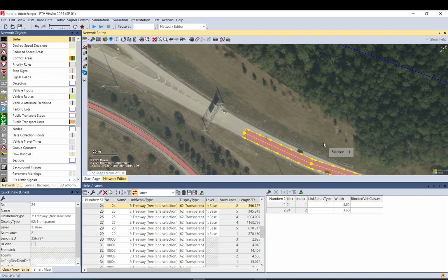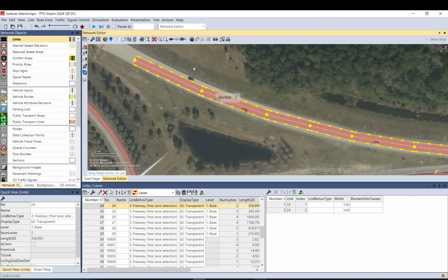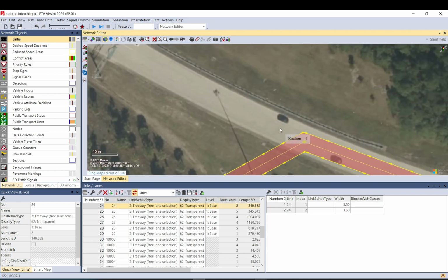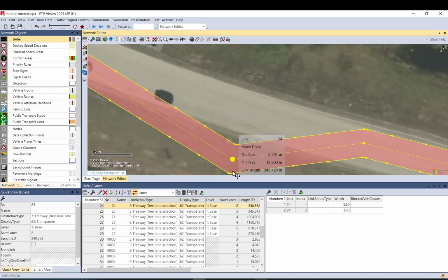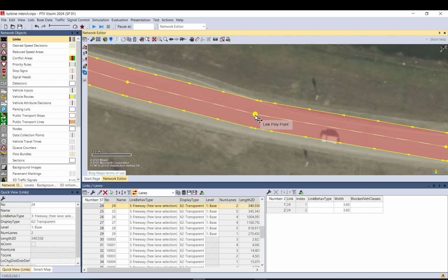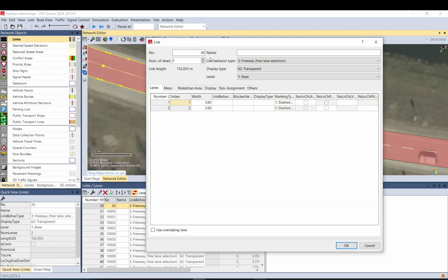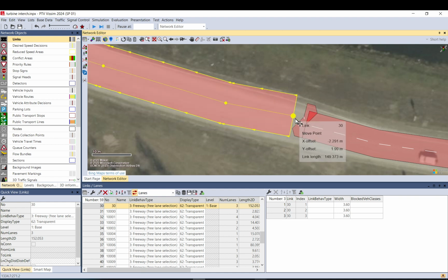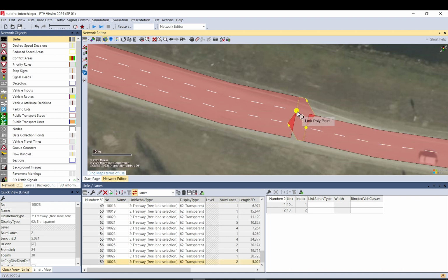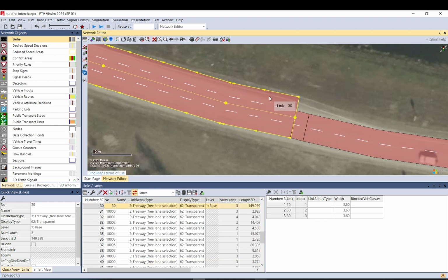So what do we have here? There is a 3-lane widening somewhere. Well, it's amazing that I can't see anything. Okay, it is here probably. So I split that link here. I try to have that extra lane as soon as vehicles can squeeze into it, plus a few meters. So when a vehicle comes here, it can squeeze in already here in maybe 3, 4, 5 meters, and you can just add this extra for that. So I would allow this. If a vehicle can get into this lane in a queuing situation, you should have that lane here in the model.